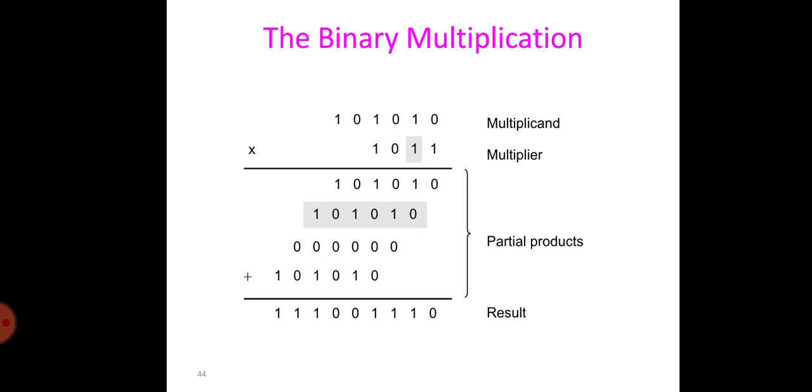So the simplest way to perform a multiplication is to use a single 2-input adder. For inputs that are m and n bits wide, the multiplication takes m cycles using an n-bit adder. And this shift and add algorithm for multiplication adds together m partial products. Each partial product is generated by multiplying the multiplicand with a bit of the multiplier, which is essentially an AND operation, and by shifting the result on the basis of the multiplier's bit position.